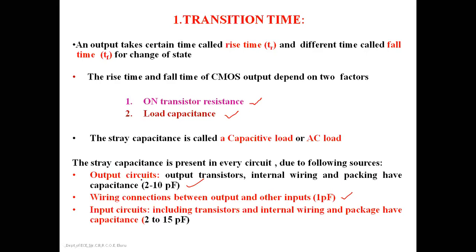When an output is connected to another stage's input, in that stage also we will have transistors, and those transistor terminals also model stray capacitance here. The internal wiring of those transistors and the packaging of that circuit will also realize stray capacitance.